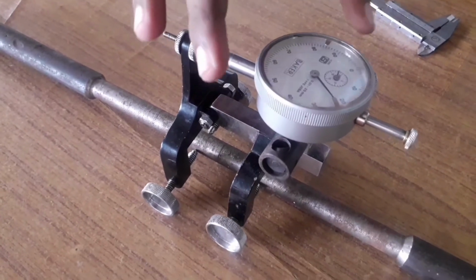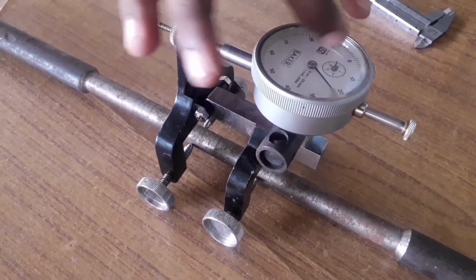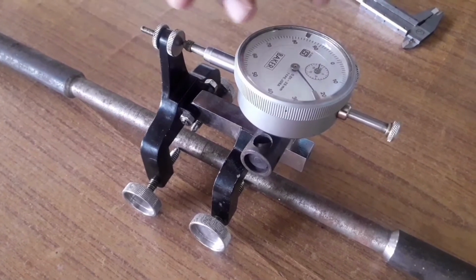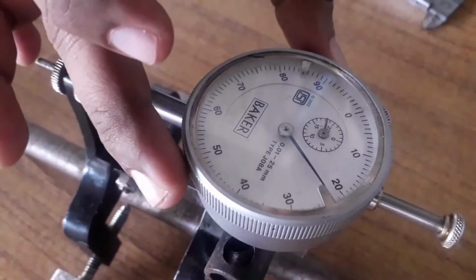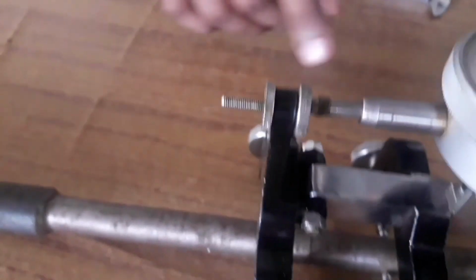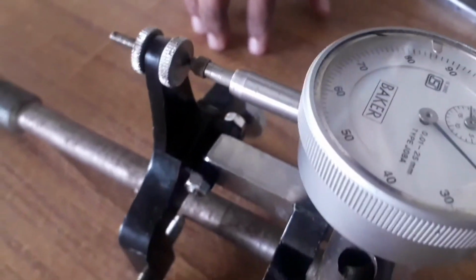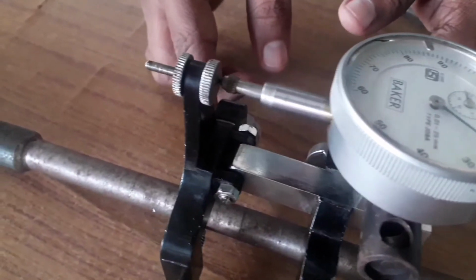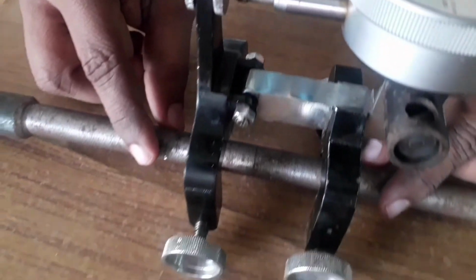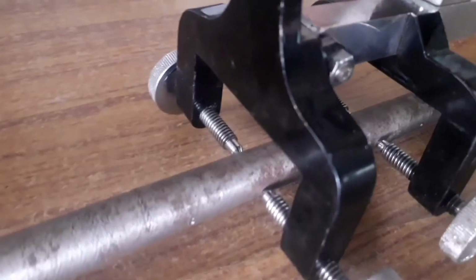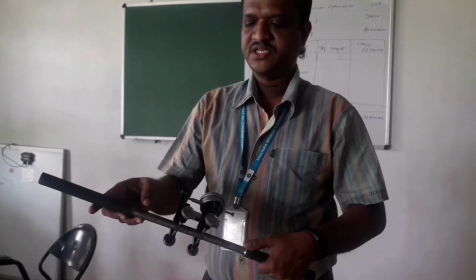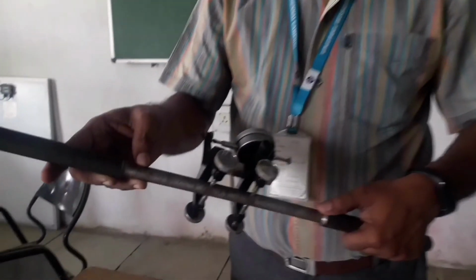Here there are two dials available. One is small, another one is bigger. This dial gauge is fitted in this extensometer, and the extensometer is connected to the specimen. Actually, this is the experimental setup. Once we measure the gauge length and diameter,